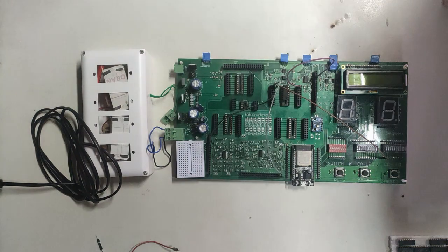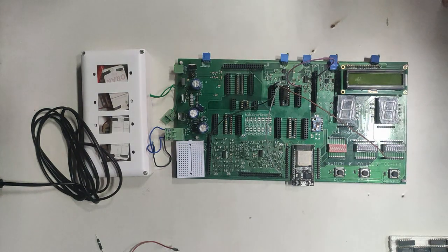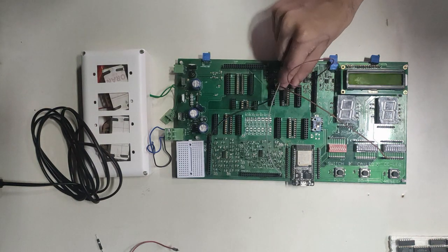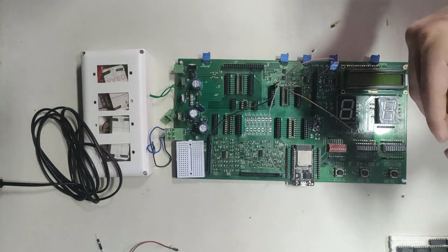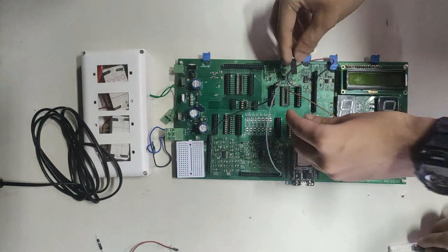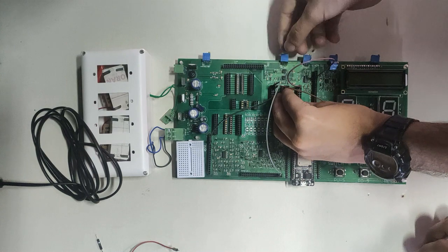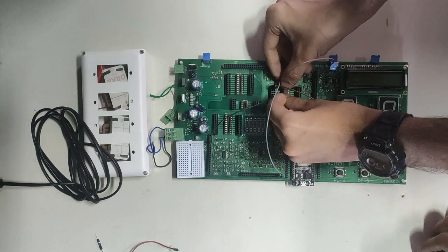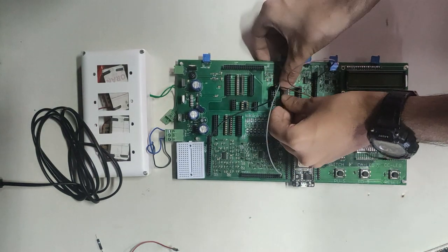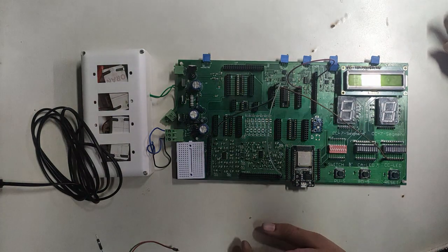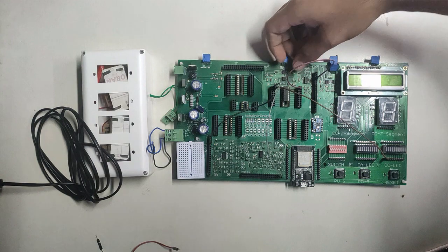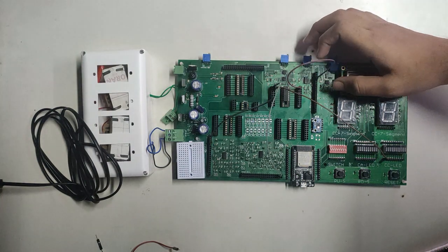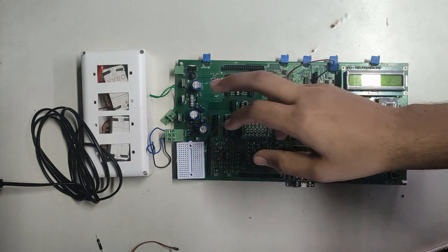After verifying the truth table of the NOT gate, we'll move on to the AND gate, that is IC 7408. I'll mount the IC in the same socket as before, since we already made the VCC and ground connections for it. Looking at the pin diagram of IC 7408, pin number 14 is VCC or plus 5 volt. Pin number 7 again is the ground.